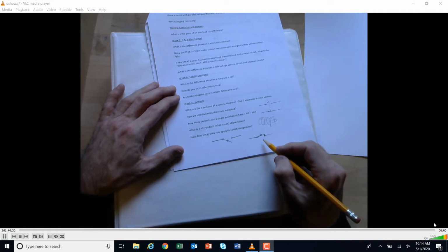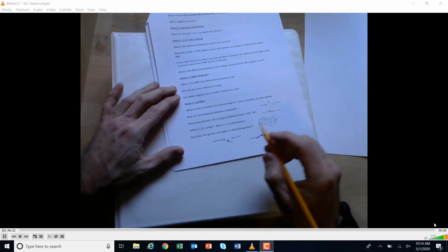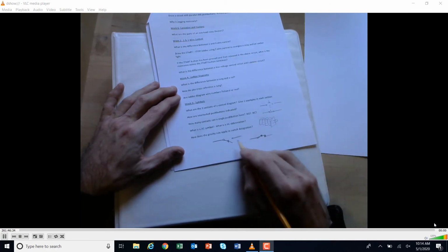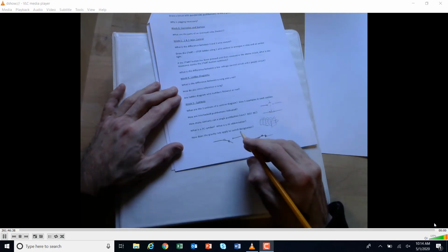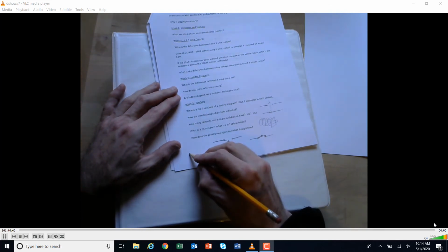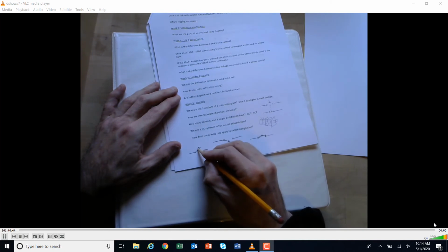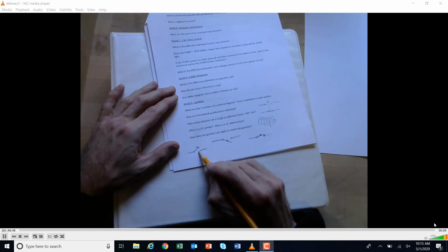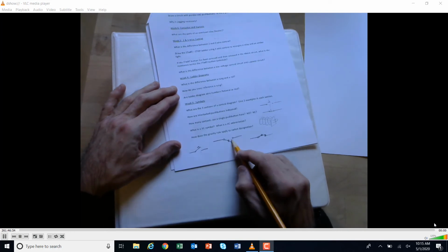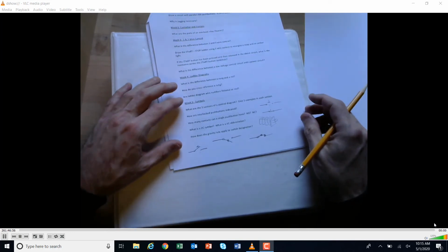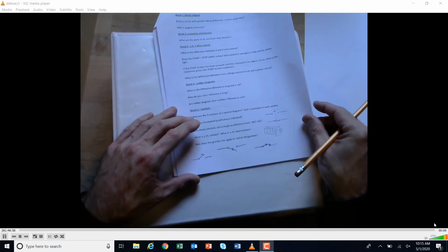And then we talked about a lot of switches look like this with the gravity rule, but there's a few that don't apply to the gravity rule, like the foot switch, where, like a sewing machine, you would slip your foot in there and you would press it and it would close. So in this case, the gravity rule doesn't apply because this is a normally open foot switch right here, okay? But most of them apply the gravity rule, and we study that quite a bit.